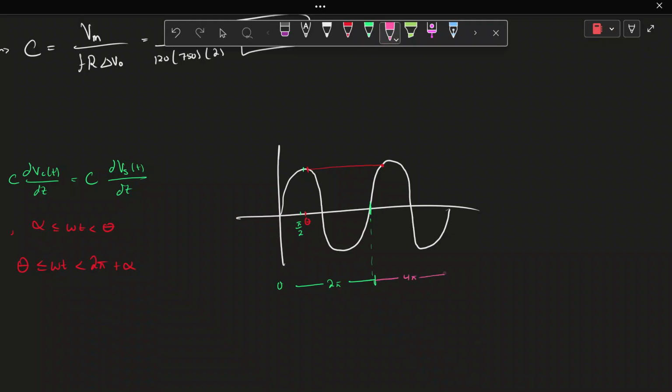This is going to be from 2 pi, and then it's going to be 4 pi. That doesn't mean the distance is 4 pi. I can rewrite this as 2 pi, actually. But this will be the first, and this will be the second period. That rectified wave here will hit the second period at an angle called the extinction angle. It's called 2 pi plus alpha.